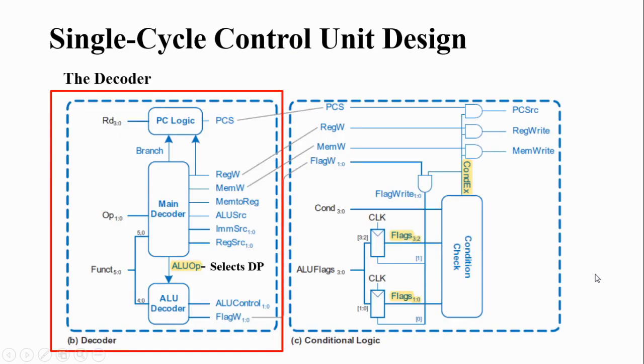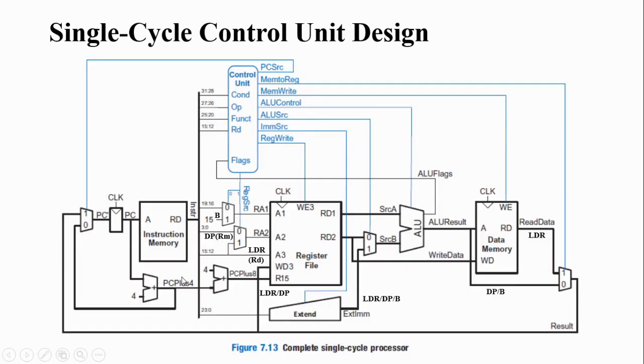You can see here, this is a circuit diagram. So say R15 you are giving as a destination. So you are setting R15 as destination. So the address of the R15 will be given to A2, right? So A2 will be selecting the destination as R15, and whatever value you are writing should be written to this, right? So this is a destination R15, not this, there is a mistake.